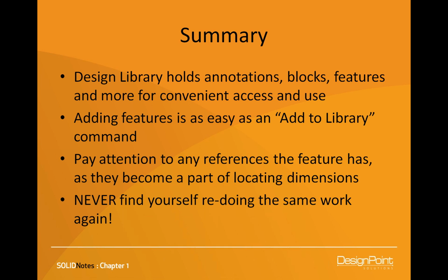Adding features is as simple as one property manager. There's just that one button you click, add to library. You have to tell it what you want it to add, and it's really as simple as that. But of course, I showed you another way to do that as well. As almost anything in SolidWorks, there's more than one way to do it. The most important thing when creating design library features, especially complex ones, like the one we did at the end there with that Revolve Cut, is tracking those references, tracking those dimensions. So it's important to understand the references and that dimensions folder that gets created up top, and knowing how to manage those. Naming your dimensions and tagging locating dimensions will go a long way, making it much easier for you to work with.